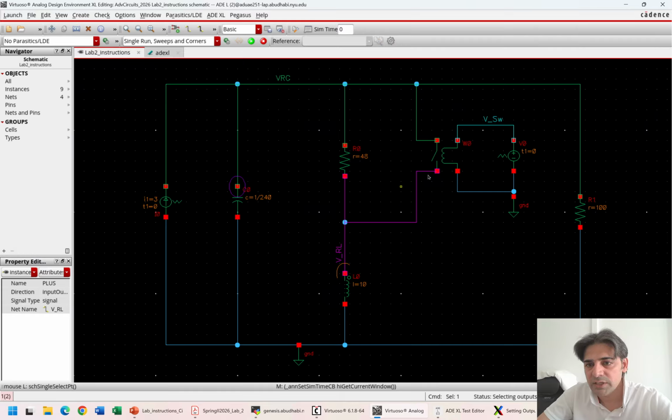This shows you that you are looking at the current at the top node. And then I'll be looking at the current of this R12, and I want to look at the current of this node. Why do I want to look at this current node? I want to see that my setup of the piecewise linear current source, which was 3 amps all the time, and at one moment this current becomes 0.